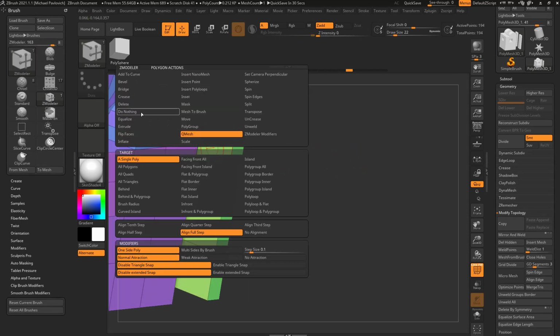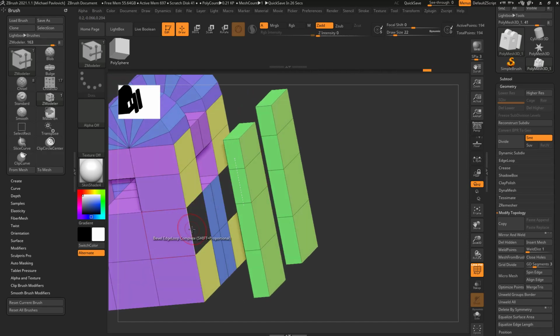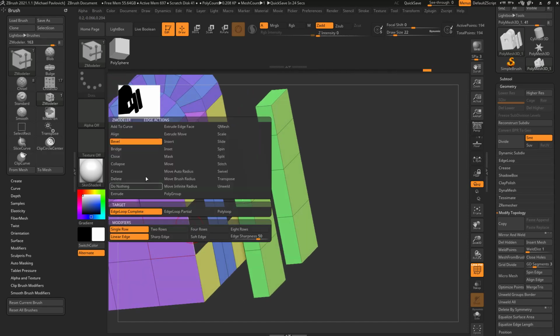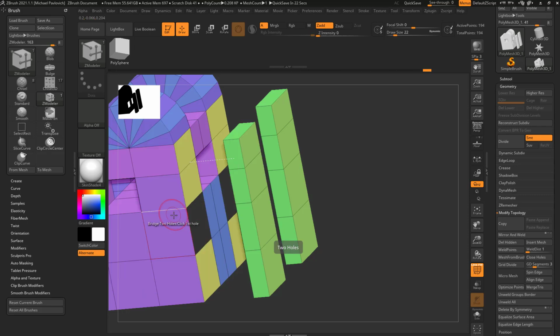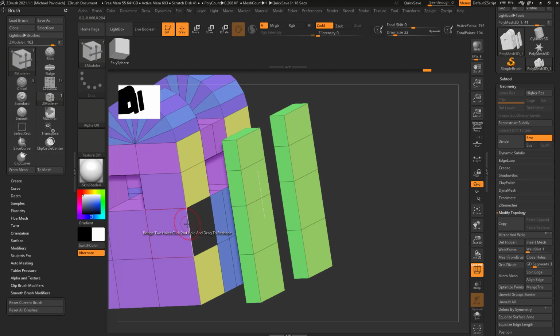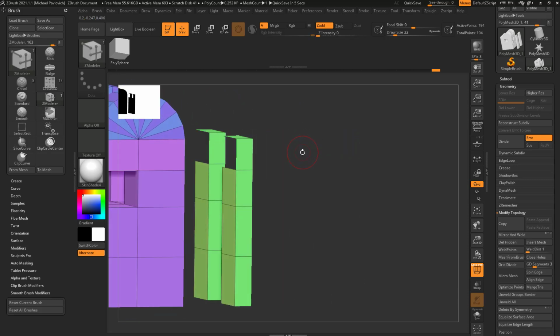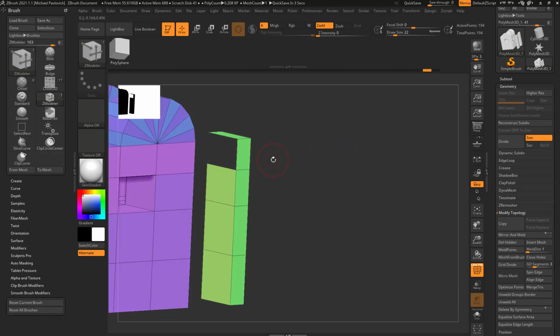However, I can also say delete a single poly, let's say this one and this one. I can now hover over an edge and say bridge two holes, and now I can bridge that hole. I just click that edge here and it says click the first hole, and now click the second hole and drag, and now you can see I can change the curvature here, and I can change the resolution if I want. So that's another way you can use a bridge function that doesn't rely on just faces.